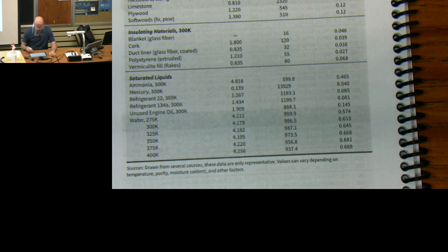Okay. So I'm going to say here the water is initially at a temperature of 40 degrees Fahrenheit. Maybe it's a cool fall day. It's been sitting outside, 40 degrees Fahrenheit, and your iron temperature is going to be 1540 degrees Fahrenheit. Very, very, very hot. And we're going to throw that iron into that water, and we're going to quench it, which means that there's going to be an equilibrium temperature that's reached. And I want to find out, what is the final temperature of this water?